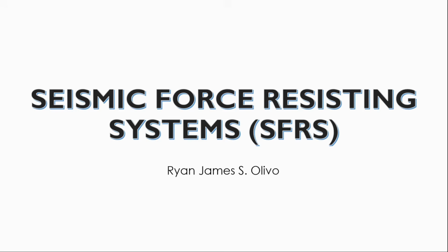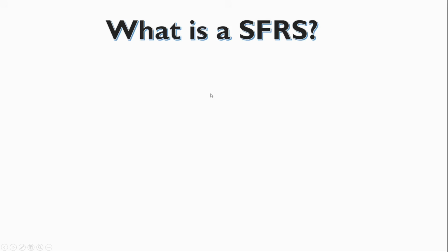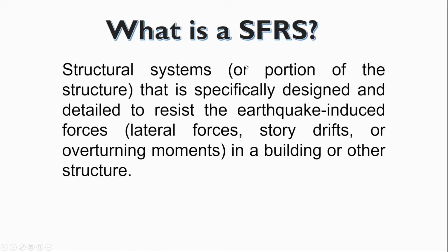What are these systems? First, let us define what a seismic force resisting system is. These are structural systems, or just parts of the structure, that are specifically designed and detailed to resist earthquake-induced forces, for example lateral forces, story drifts, or overturning moments in a building or other structure.